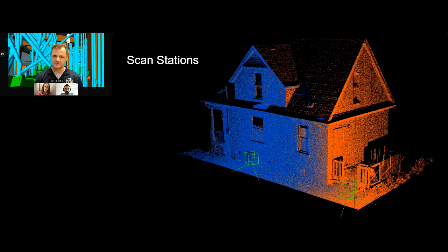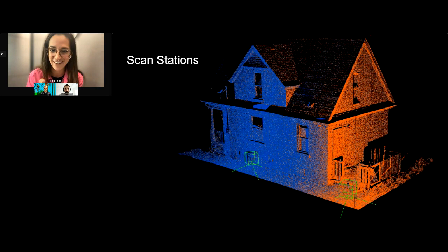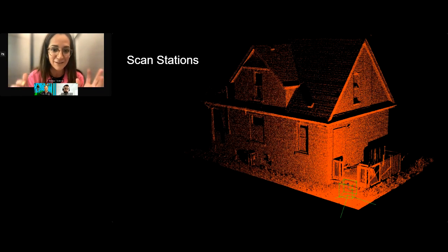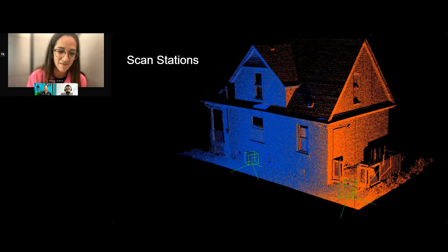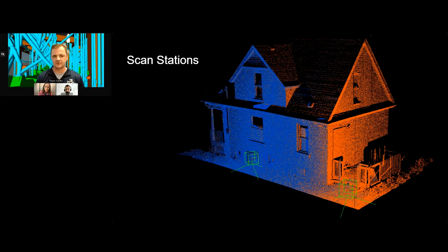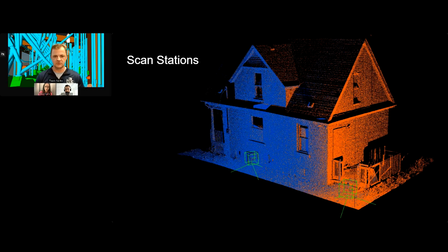And this goes back to, if I can add here, because I think Ted talked about this in the photogrammetry section, this comes down to good planning as well. Before you go on site, you really need to plan this in advance. Yeah, so you have to know, we always say, what are you doing with the scan? You have to know what you're doing with the scan. You'll have to make sure that you have a clear line of sight to everything that you're trying to scan.